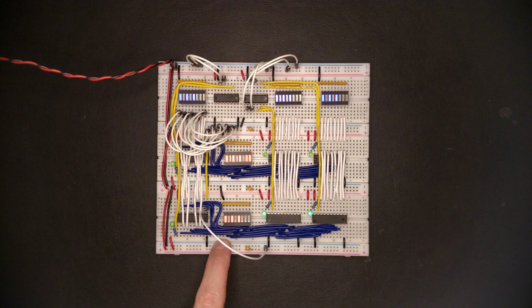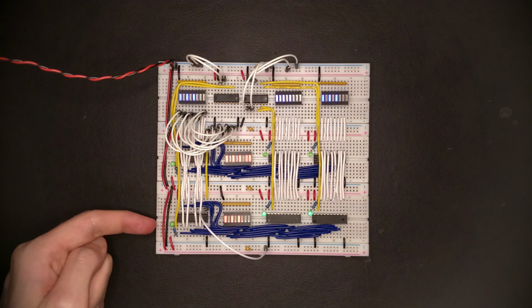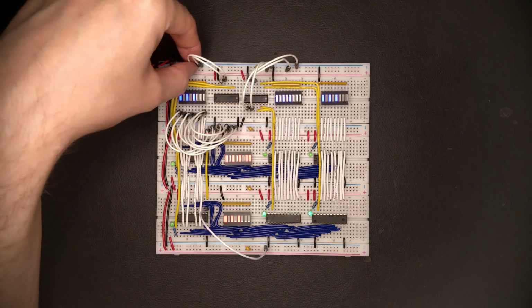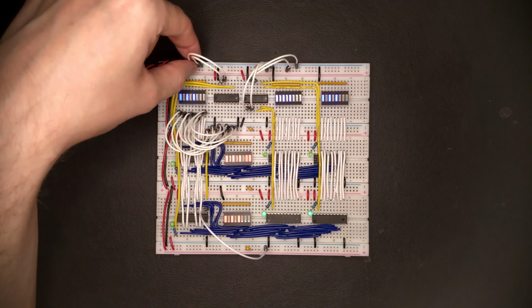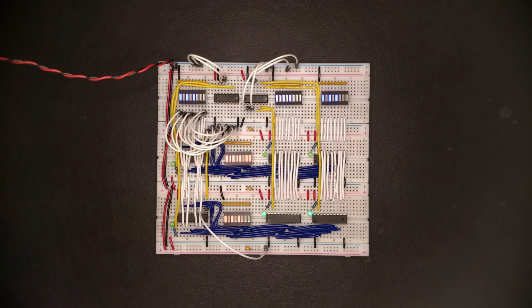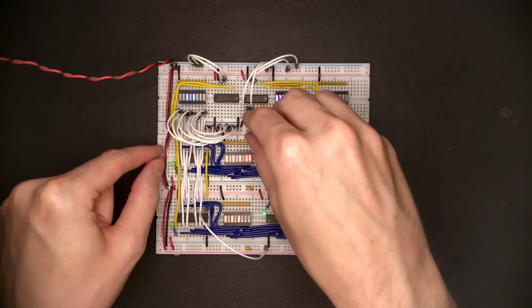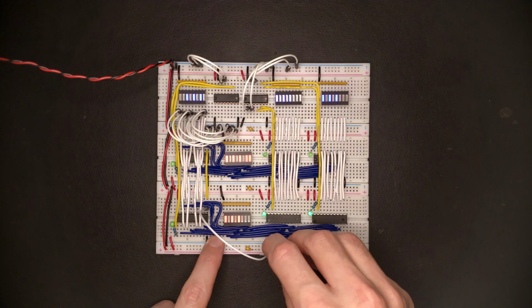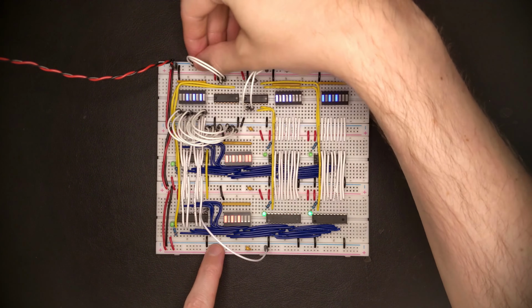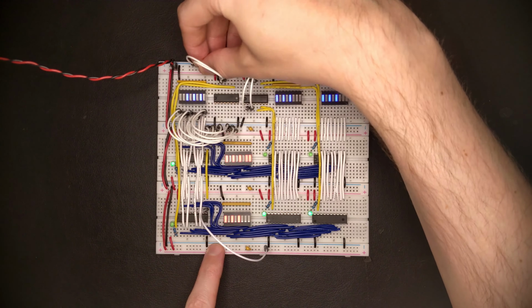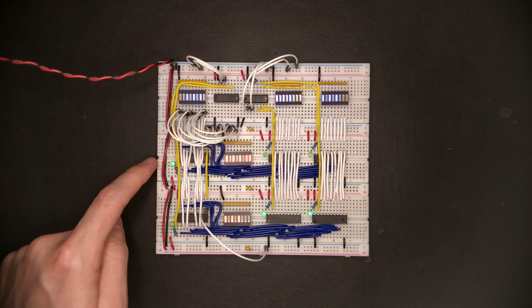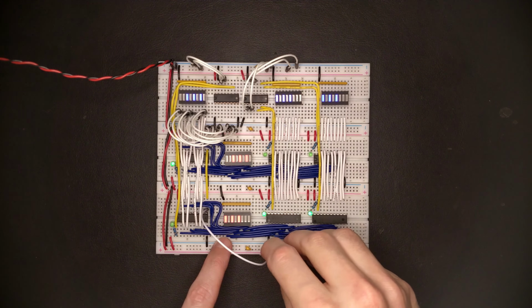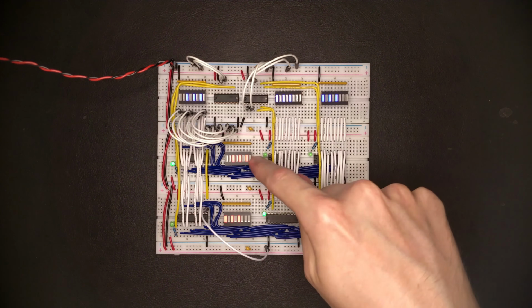And in terms of writing, none of the registers is currently selected because we're applying write address 0 here, which is basically saying don't do anything. Well, let me change the pattern a bit. And now toggling the clock doesn't do anything. But if we select register 1 for writing, you can see that the write enable of the first register goes high. And when I toggle the clock, the new value gets latched in.